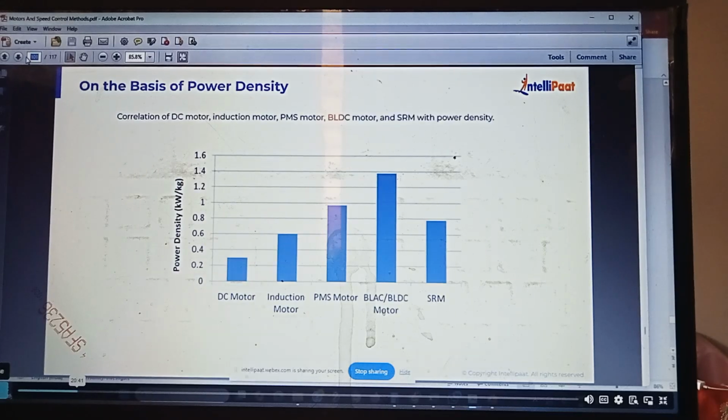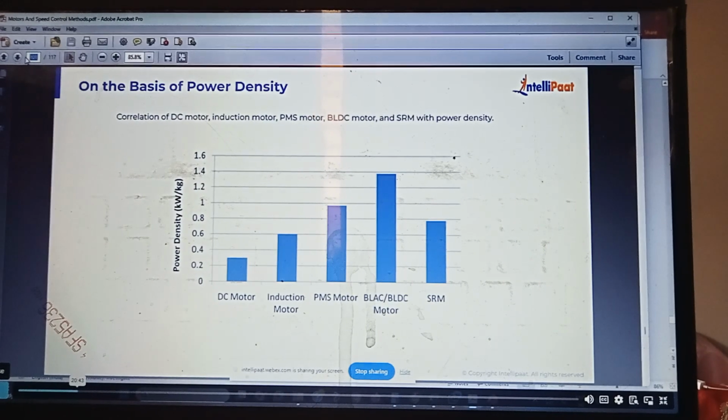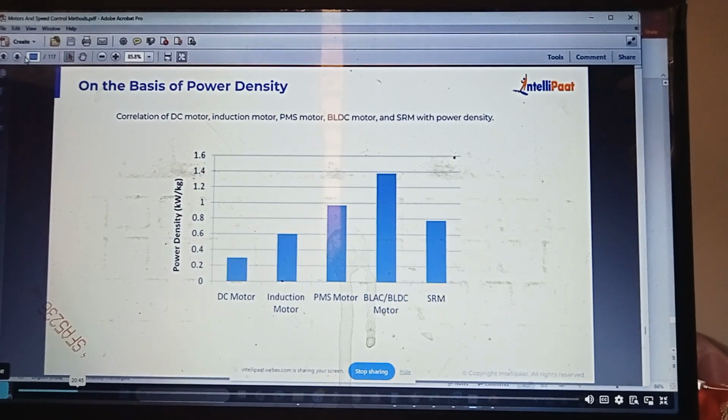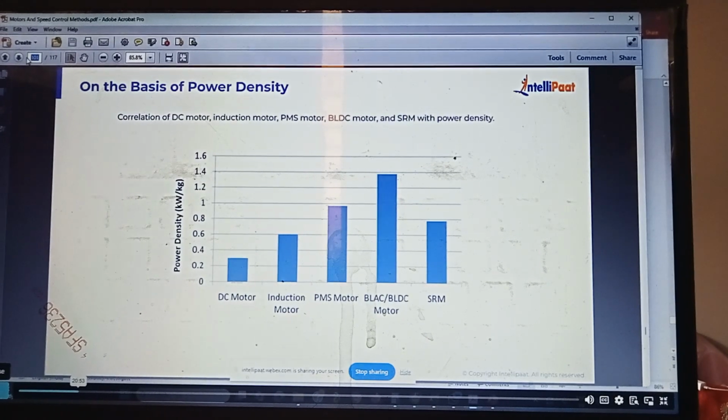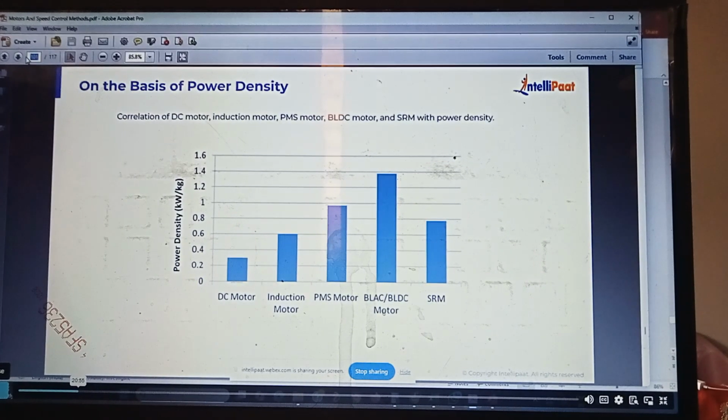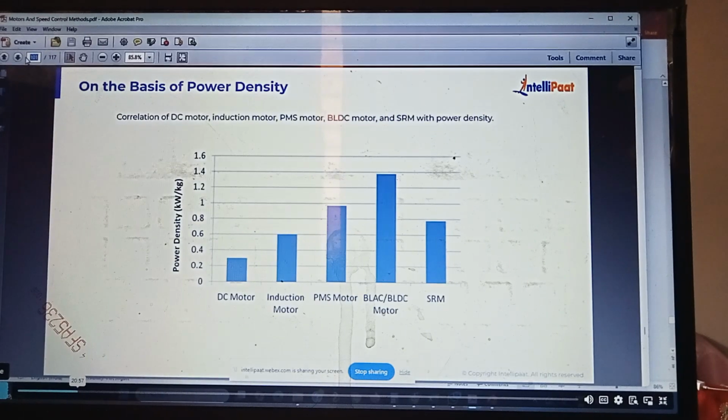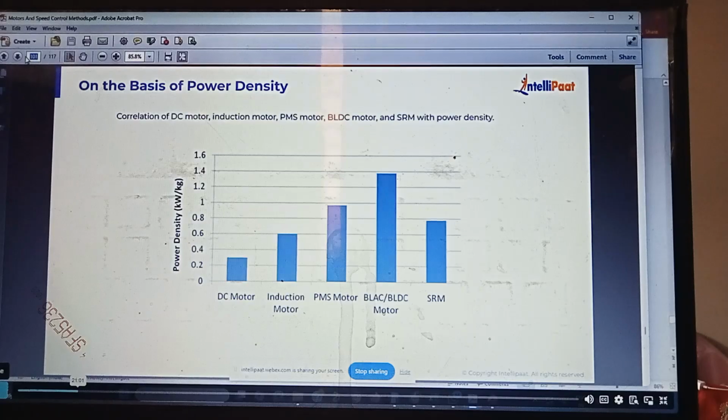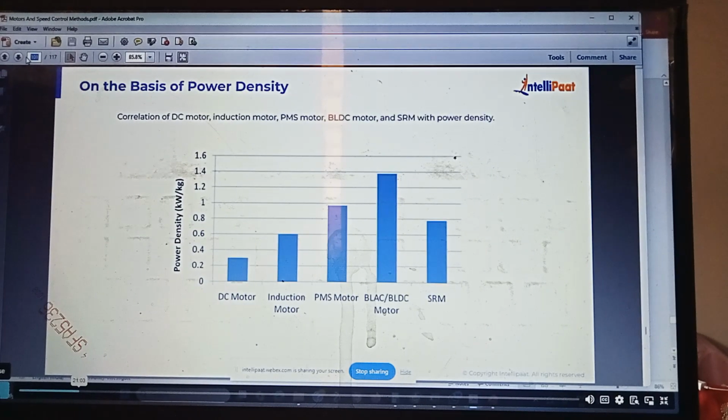And generally DC motors have higher size requirement, higher volume requirement, all those problems. So majorly due to maintenance requirement and restriction on higher speed, that creates a problem for the DC motor. So the motor which does not have this brush and commutator requirement is preferred for EV application.